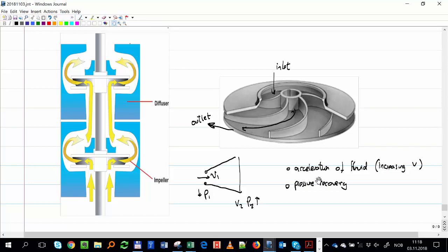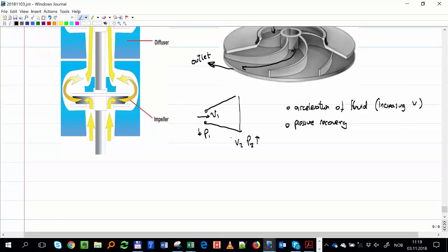So part of the diffusion, the acceleration, is made everything on the rotor. The rotor is rotating and accelerating that fluid. And part of it, if you see this shape, here is small, and then at the end it has some expansion. But it cannot expand everything. What happens if you try to expand too much in a very short distance? Let's say this configuration versus this configuration.